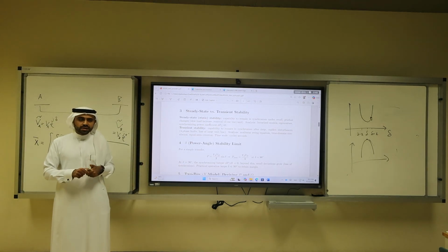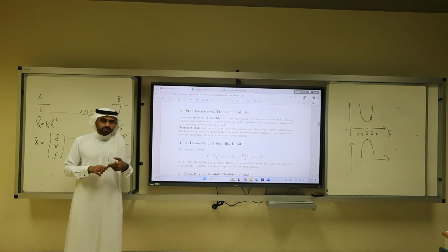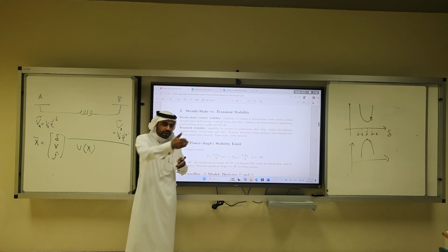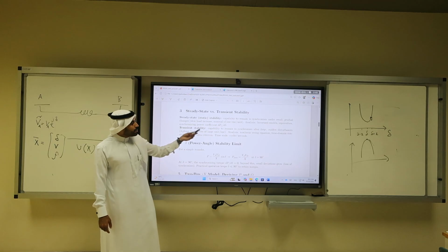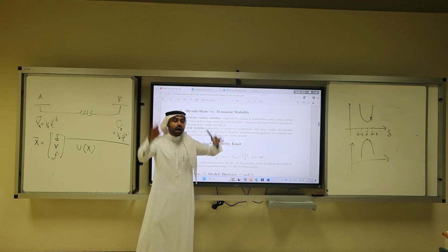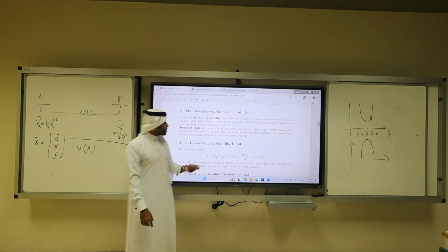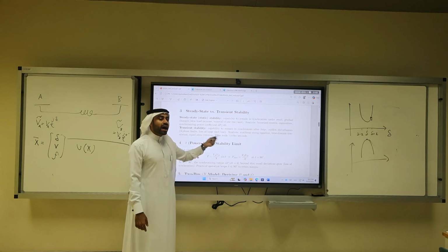Is there a course called dynamic? Yes. Dynamic is similar to transient. It's 522. What will happen in 522 is the capability to remain in synchronism after large events, big faults in the system, for example three-phase faults, or loss of a large generator.